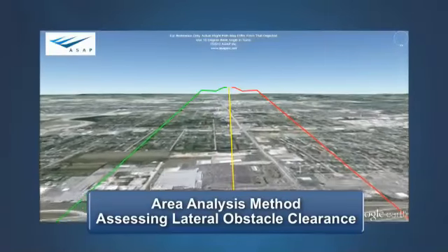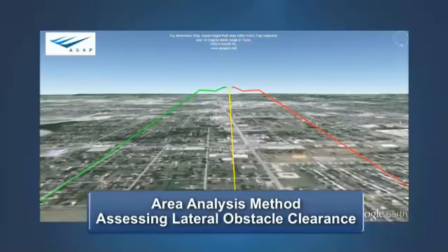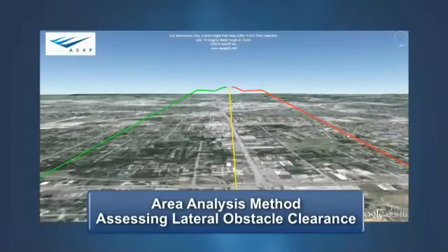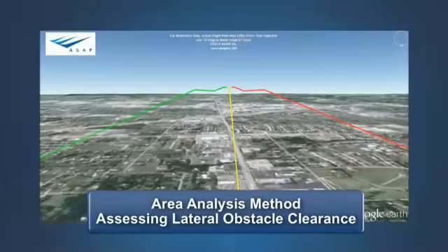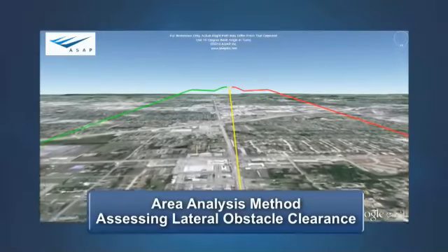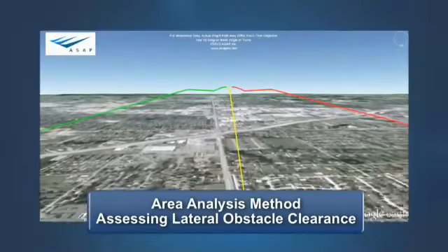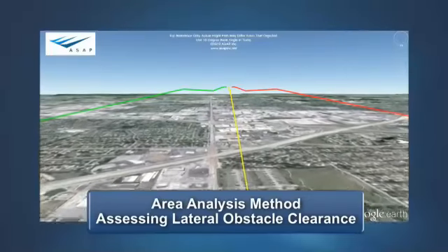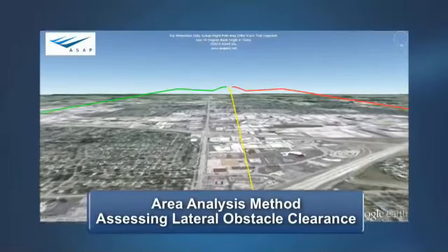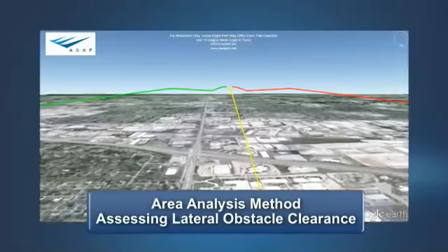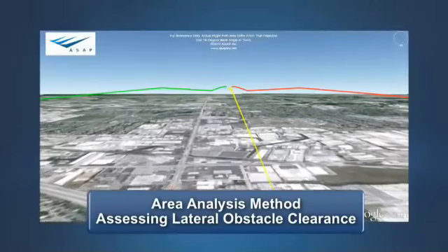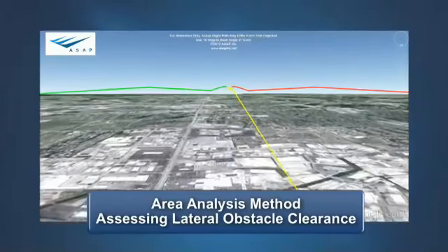This is accomplished by using an obstacle accountability area within which all obstacles must be cleared vertically by the net takeoff flight path. For an engine failure procedure that is centered on the extended runway center line, this area begins at the runway end and expands at a predefined rate until it is at a maximum width 2,000 feet either side of the intended track.